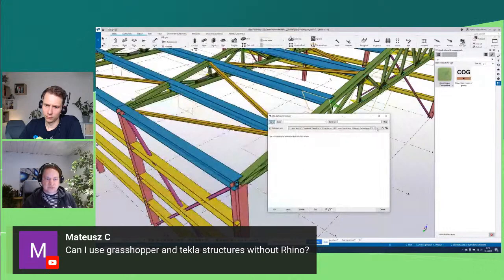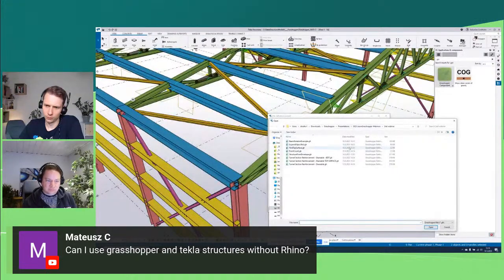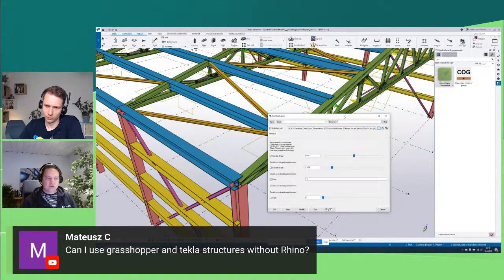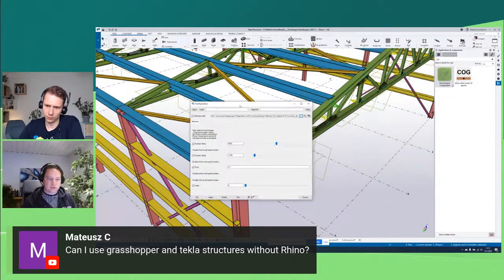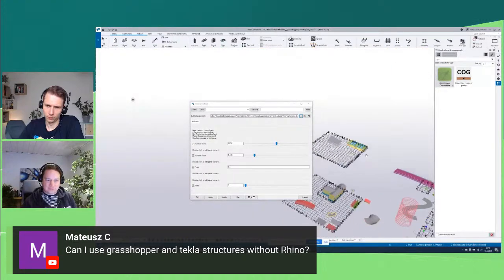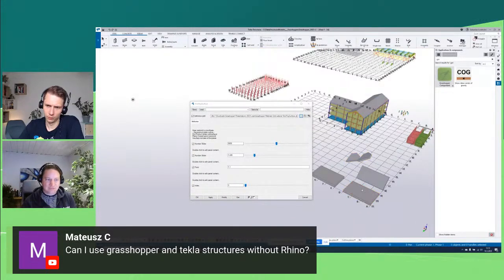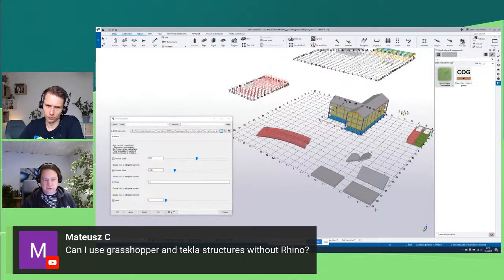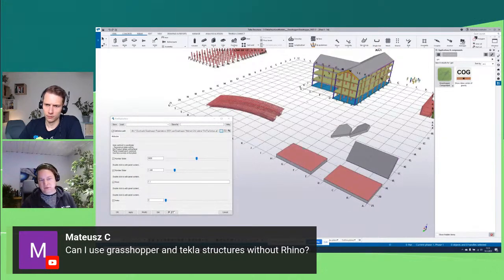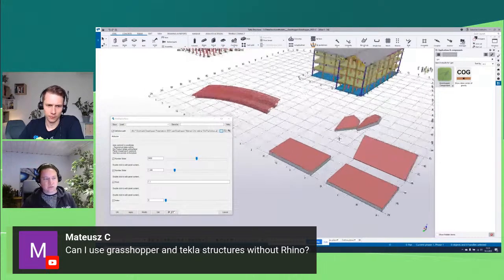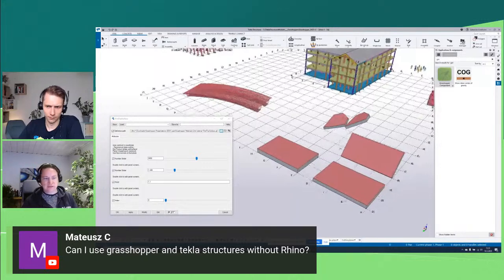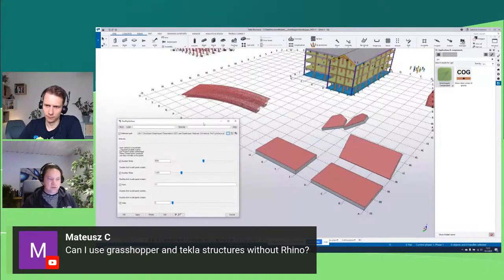And let's see what happens if we load it into the Grasshopper component. It was that one. Because I didn't filter the attributes, we got all kinds of stuff here, but regardless, if I now insert it, it does run that Grasshopper script in the background without anybody needing to see Grasshopper or Rhino. And it will start Rhino automatically if it's needed. So that's one way to use Grasshopper without seeing Grasshopper or Rhino.